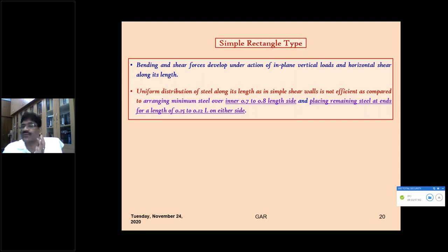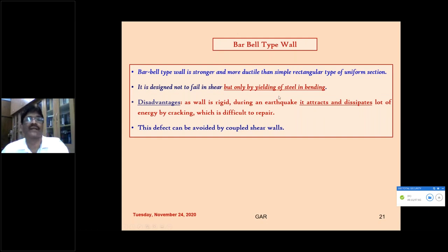If you can accommodate reinforcement in the end regions, they will act like a special vertical element acting integrally with the nominal wall. So that is more effective than the wall provided with nominal distribution. Then the end regions of the plain wall can be enlarged. That means a flange can be created, or the thickness can be increased so that an additional head or bulb can be created. Or in the plain wall itself, the reinforcement concentrated in the end regions will have more stiffness compared to elsewhere.